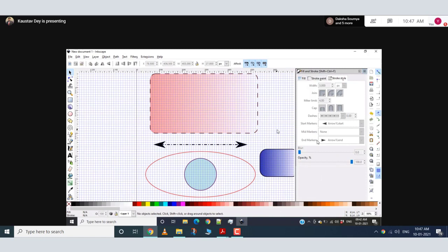If you want to preserve the height and width ratio, that is the aspect ratio of your shape, suppose you want to preserve the square or a circle, you should either do the stretching by pressing Control or by the lock icon, by locking the aspect ratio as Kevin had suggested. So either of these two you can use. Then we have seen how to alternately edit the lines by using the edit by nodes. So if it's a straight line in particular, you can very easily make the straight line edit by nodes and get over with it, because it does not in that case change the line width.